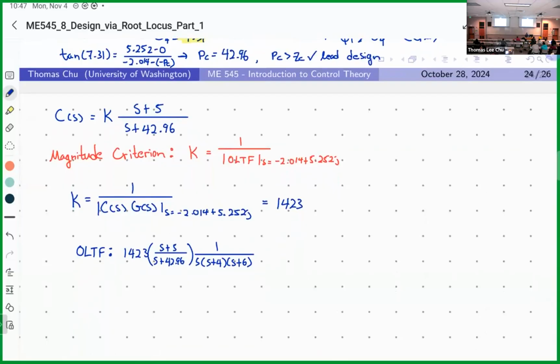Okay, so I have in MATLAB coded up the lead compensator, and we can compare it to the PD compensator. Just a reminder, the uncompensated system had a settling time of 3.97 seconds. And we're aiming for 1.99 seconds or better and 30% overshoot. That's what we want.